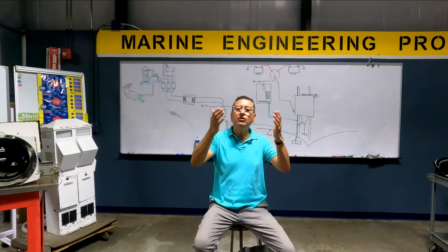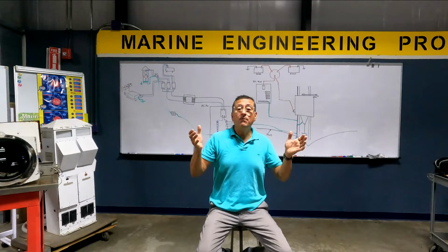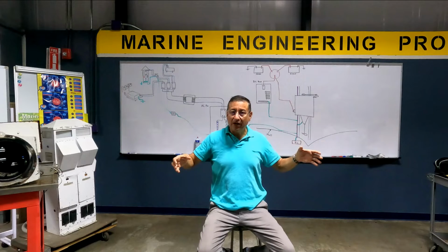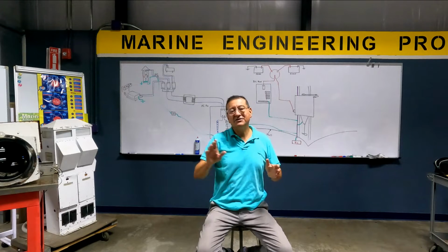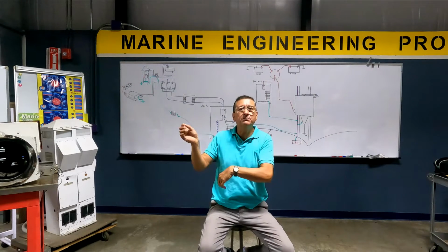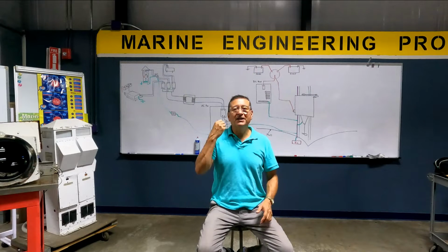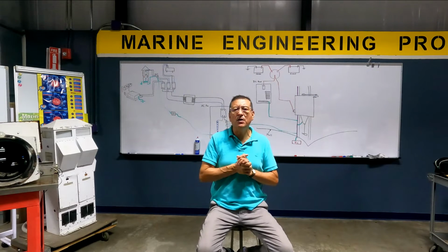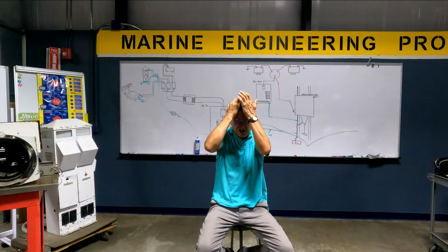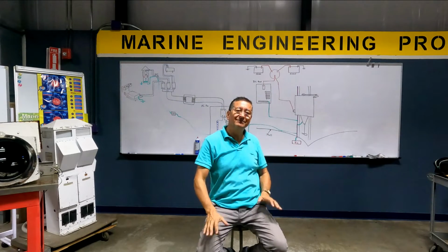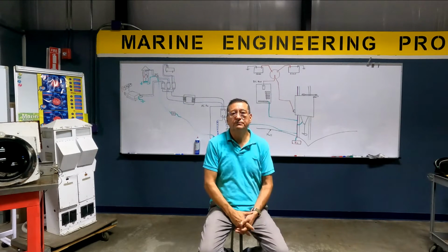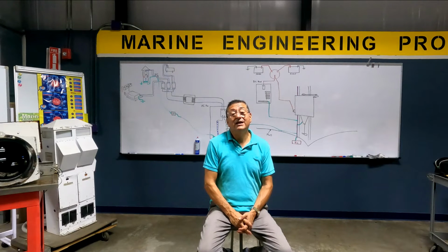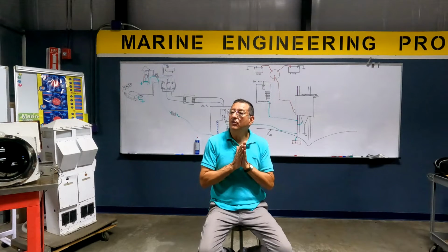For example, it's common that you have a boat with two engines, starboard engine and port engine. The port engine is properly bonded to the bonding conductor, and the starboard engine is not. The bonding cable is broken. And you receive a phone call from the customer: I don't know what happened in my boat. The port side of the boat is corroded and the starboard side is clean. It's because the connections on that side are not good. That's the reason. The bonding is necessary. It's mandatory. Okay, this is number one.